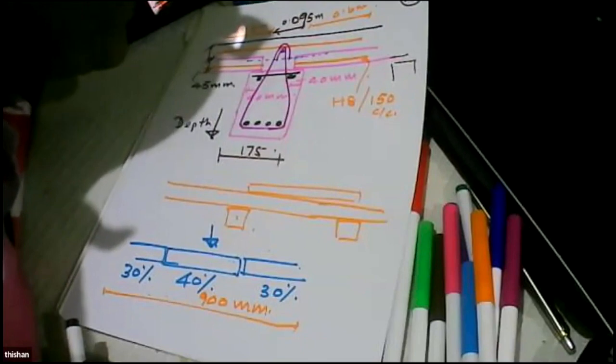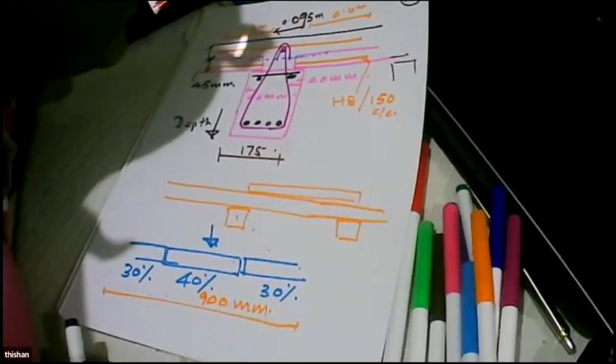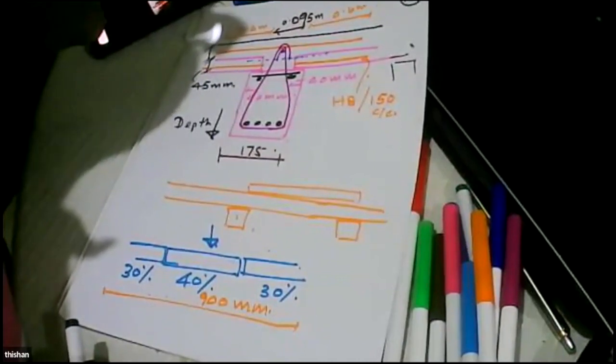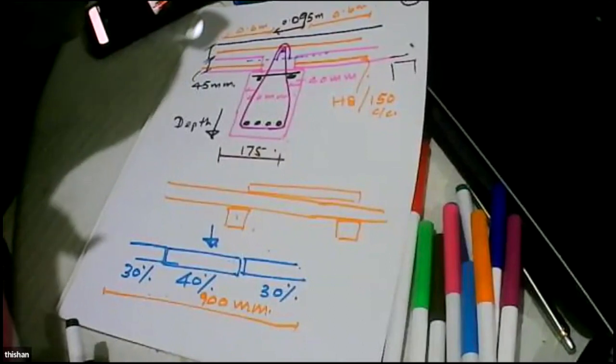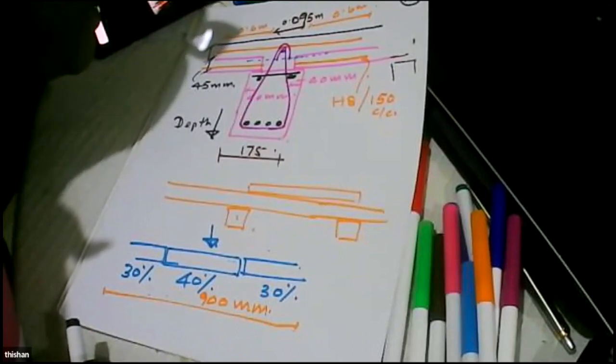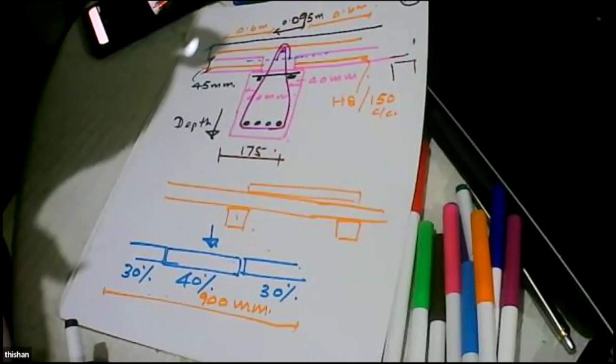No, we have selected 15 millimeters as the minimum according to Eurocode, because we are using high strength concrete. And this is very high strength concrete, compacted very well. And we can easily cure the steps, because after about 24 hours you can make it vertical and then carry it.